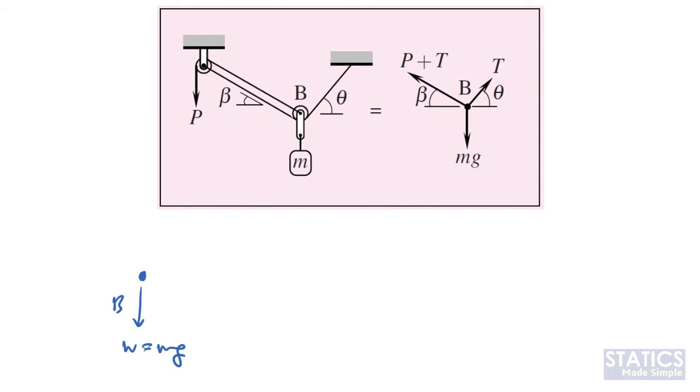Let's say for the first cable here, the tension is given as P. The second cable, tension is unknown. Let's say it's equal to T. So at point B, we'll have T at the angle of theta, and then here we have P. And for the other cable, we'll have T. So that means we have P plus T here at angle of theta with respect to the horizontal axis. What I'm drawing here is your free body diagram for point B.